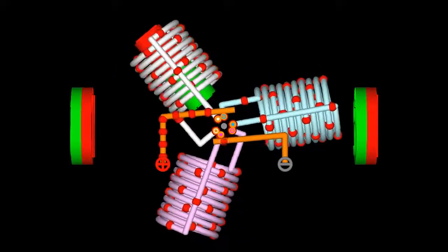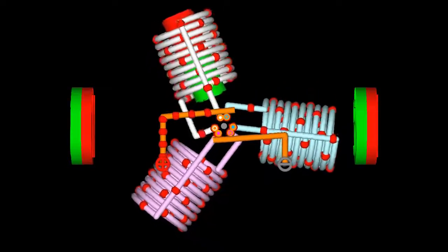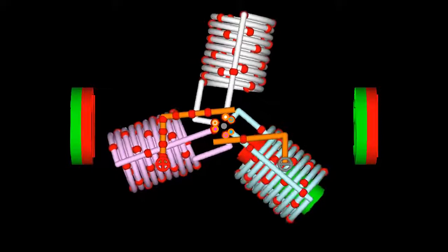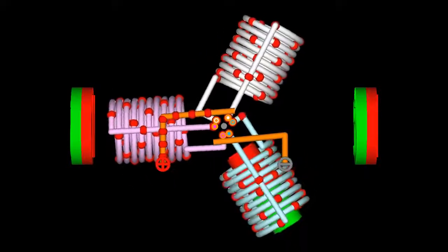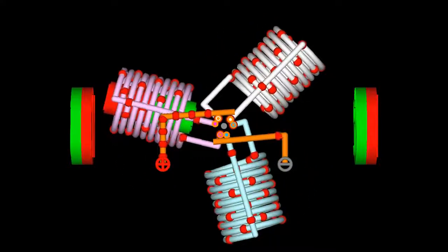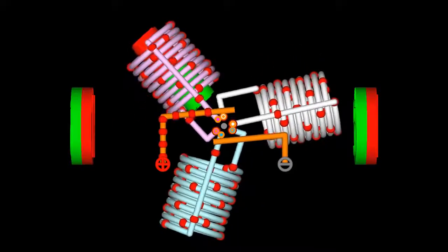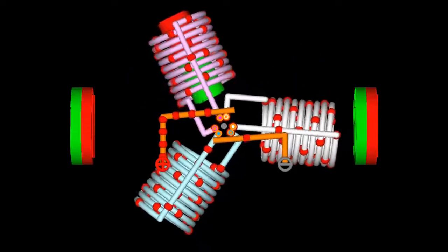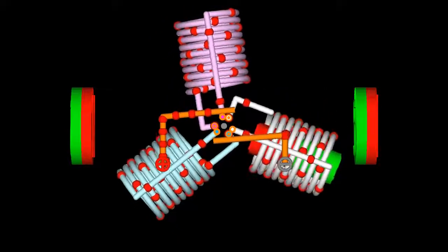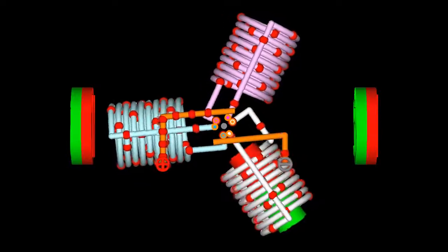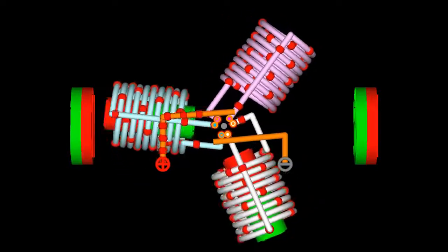Even 3 electromagnets are sufficient to make an electric motor spin continuously. At the commutator, each end of each coil is connected to one end of the nearby coils. The commutator switches from one electromagnet to the next, each 60 degrees. For a short interval, 2 coils are energized simultaneously.